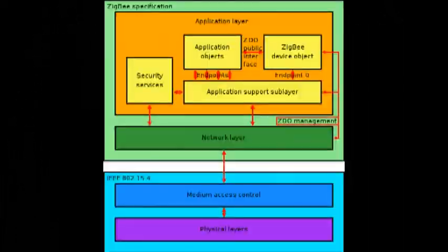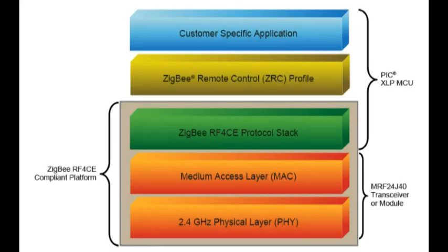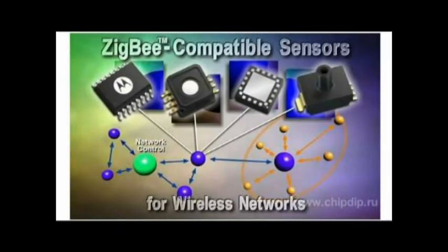Besides adding 2 high-level network layers to the underlying structure, the most significant improvement is the introduction of Zigbee device objects. These are responsible for a number of tasks, which include keeping of device roles, management of requests to join a network, device discovery, and security.